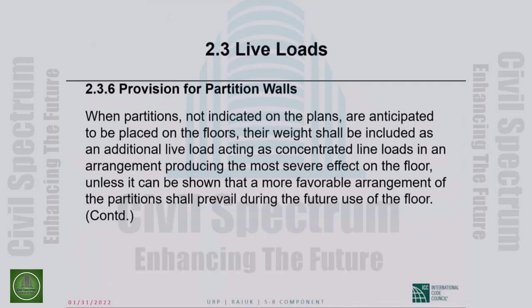The partition walls, the movable walls that I was talking about: when partitions not indicated on the plans are anticipated to be placed on the floors, their weight shall be included as an additional live load. This is a live load acting as concentrated line loads. This again is not what I typically see.